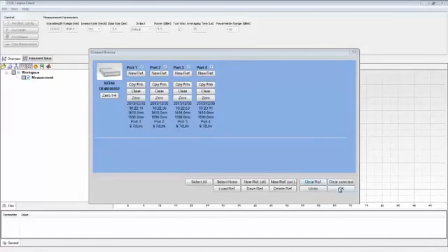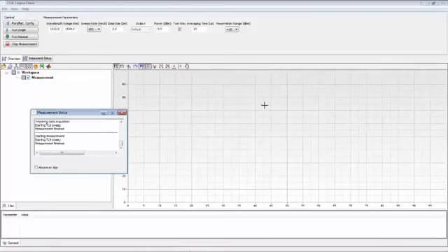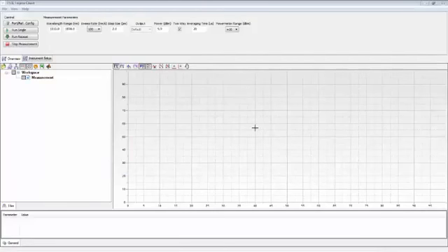So now we're ready to actually connect up a device and make measurements. So let me take a minute to connect up the device, and then we'll start making measurements here shortly. And so I have a device connected now. I'm looking at 3 channels, which are part of a 4-channel WDM mux. And in order to acquire data, I just need to either select Run Single, which runs a sweep once, or Run Repeat.